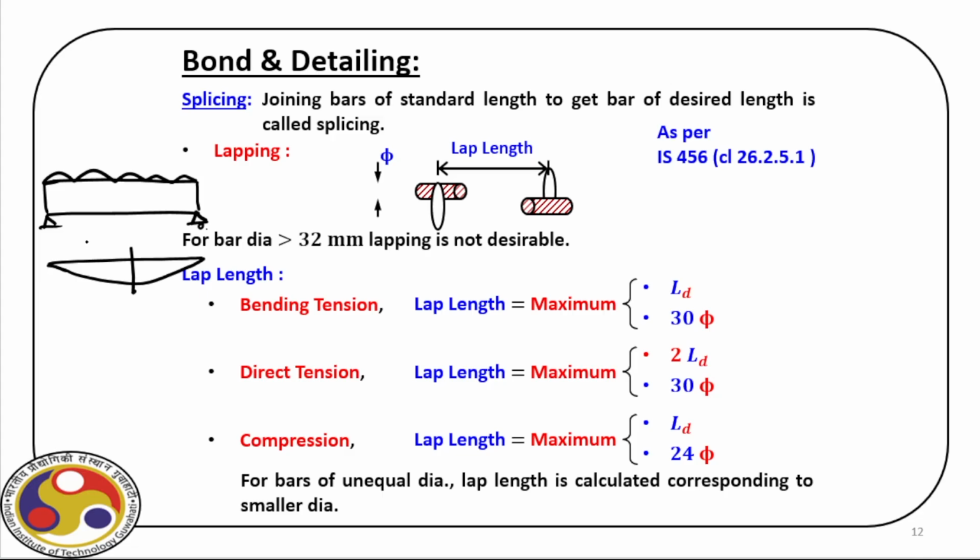If we go towards the two ends, the bending moment requirement is much less, and ultimately 0 at the two ends because of simple supports. Now, if we design this beam against this value of applied moment, then obviously the amount of steel we estimate, we provide here, but as we go towards the end, the requirement of steel is less. So after a certain point, we can reduce the amount of steel, and that is what is done using splicing.